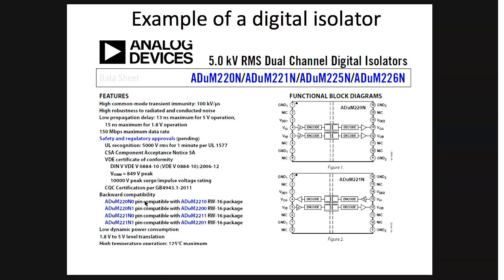Even for communication circuits you can buy isolators. You can isolate the signal, not only power, DC. So you should know, isolation mostly means you will be talking about only the DC part, but there are some design requirements where you need to isolate the signal itself. You don't want this signal ground mixing with this part, but you want the same signal through. Then you can use a digital isolator, or if it is analog, then you can use one accordingly.